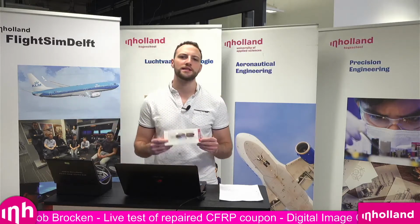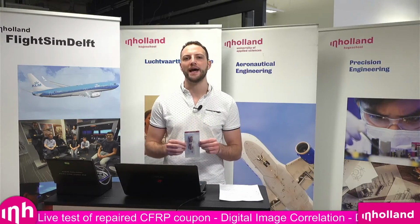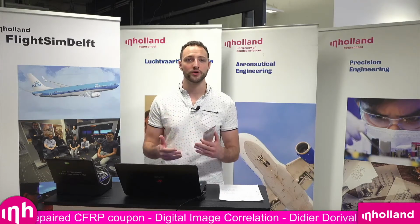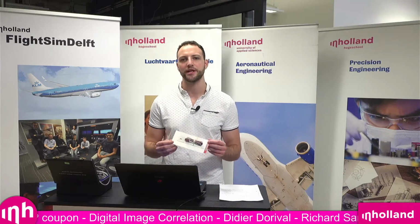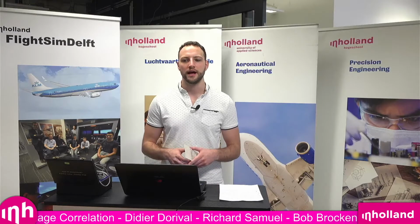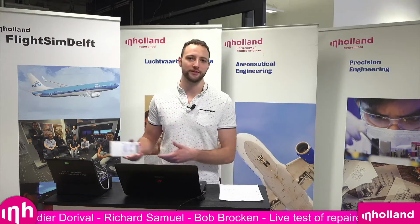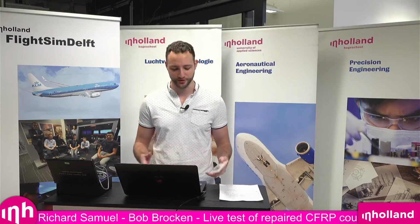The issue with the contact type extensometer is you have to manually put it on the sample by hand, and it's hard to align it exactly in a vertical or a horizontal orientation. Especially, it costs 10 euros per strain gauge, and they're not reusable. So if you're testing a sample for the Poisson's ratio, you need to put 2 strain gauges on one sample, and that's around 20 euros per sample. And if you're testing for consistency, 10 samples costs a lot of money, 200 euros already.